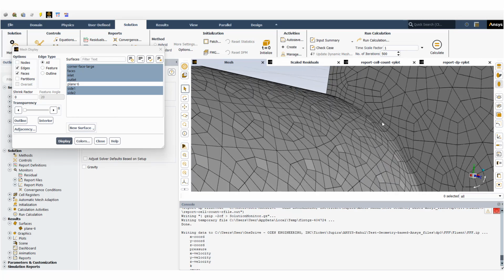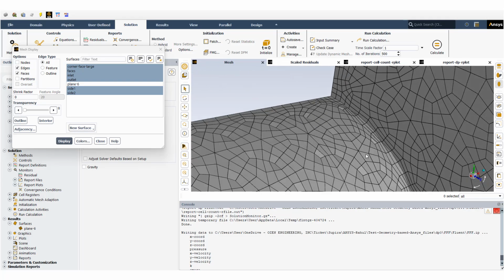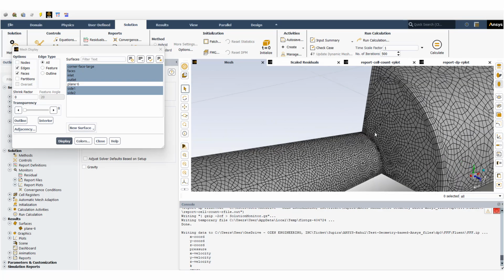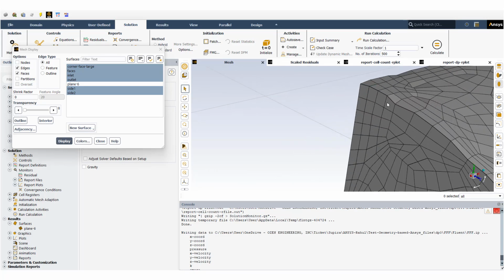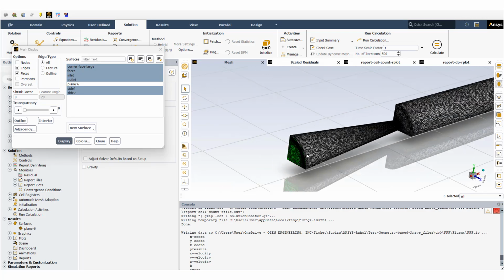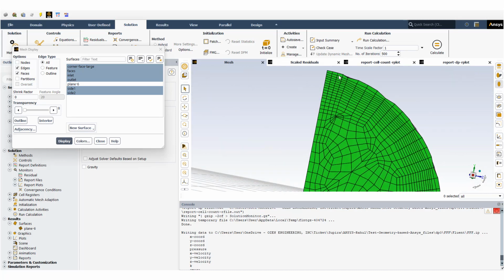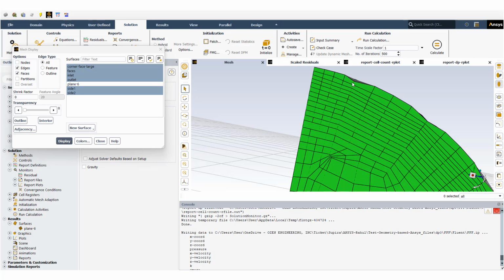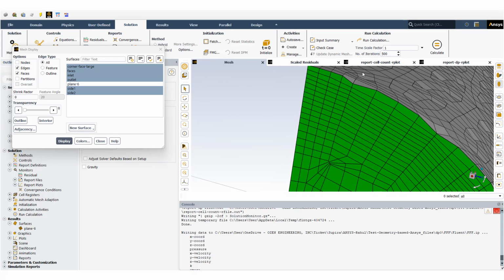You can see that here I have very good curvature, and here as well, but somewhere it is still bumpy. So it shows that even with this, we have to be careful about the resolution. And for the inlet, this is because the initial mesh is not very good quality, to which we applied this mesh adaptation.